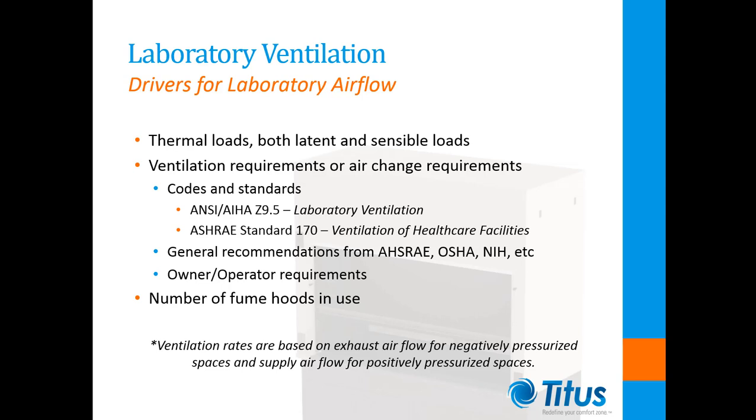ASHRAE Standard 170, which covers laboratories and healthcare spaces, sets minimum requirements for the total air changes per hour, as well as the volume of outdoor air to be supplied and room pressurization requirements. However, it recognizes that a set ventilation rate will not meet the needs of all conditions that may occur and defers to ANSI Z9.5 as long as a hazard assessment and laboratory ventilation management plan have been established.